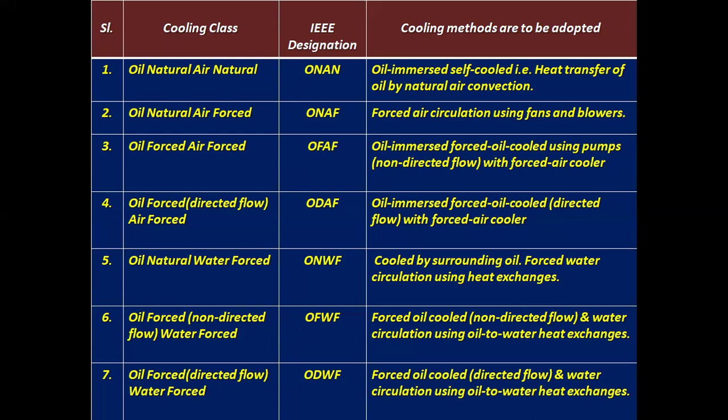Oil forced non-directed flow, water forced, OFWF. Forced oil cooled, non-directed flow and water circulation using oil to water heat exchangers. Oil forced directed flow, water forced, that is ODWF. Forced oil cooled directed flow and water circulation using oil to water heat exchangers.